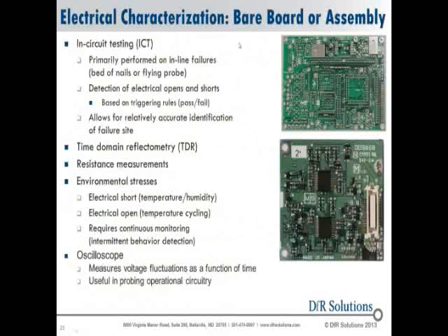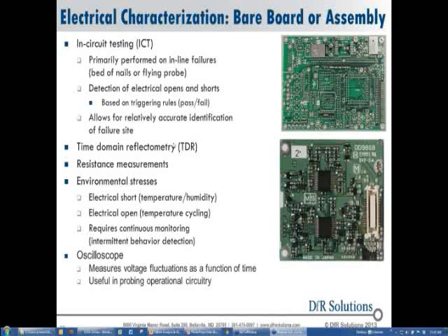When you're doing a circuit board, either a bare board or an assembled board, you usually want to be using your in-circuit test, or if you use the flying probe type of techniques for testing, if there's been any kind of disruption in the connections of the circuit board, whether it be a solder joint or a burnout trace or whatever. Now, usually this equipment is set up to be used on your production line.